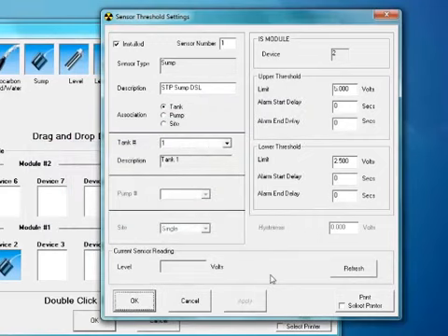It's successfully configured. So now if I click the refresh button, it will then tell me what my sensor is reading currently. This device number 2 is a normally closed sensor, so when that sensor is closed, my voltage reading coming back is 5 volts. The way the thresholds work is if the voltage that we read is above 5 volts or below 2.5 volts, then we will go into alarm.